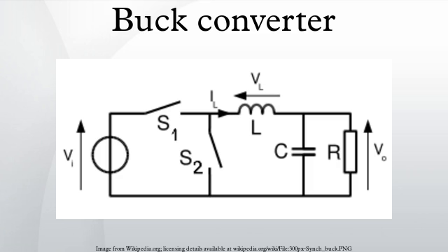Theory of operation. The basic operation of the buck converter has the current in an inductor controlled by two switches. In the idealized converter, all the components are considered to be perfect. Specifically, the switch and the diode have zero voltage drop when on and zero current flow when off, and the inductor has zero series resistance. Further, it is assumed that the input and output voltages do not change over the course of a cycle.